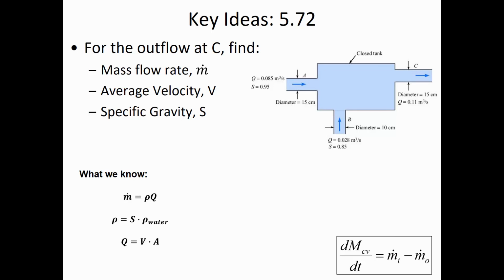And to find the mass flow rate, you're going to have to know the density of the mixture. You know, without accounting for the density of the two different inflow streams, you wouldn't be able to find the specific gravity of what's coming out or the mass flow rate that's coming out. But you could have found Q, is my point, they didn't have to give it to you. So that's why it surprises me that they did. Any questions about this one?